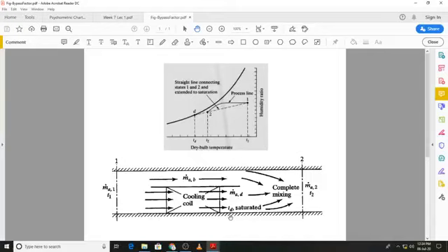One part in which the air is assumed to be perfectly cooled, that means all the particles of the air in that particular stream are cooled to a temperature Td, and we can assume that the remaining particles are not at all affected by the cooling coil and they remain at the temperature T1, as if that portion of the air has bypassed the cooling coil, and that is from where the term bypass factor is derived.